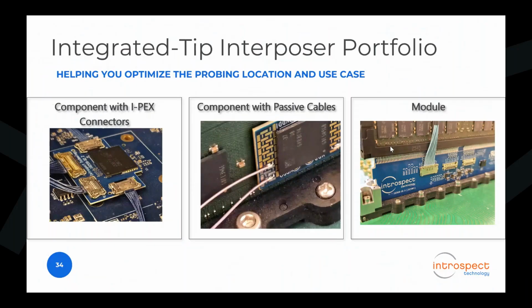So these are examples of the form factors. Like I said, we're now into the tens of form factors for them. But for the RDIMM, on the right-hand side, this is our RDIMM riser solution, and currently we boot up DIMMs at 10 gigabits per second with this, so it does pass the signal integrity check from an eye margin point of view on the system side.